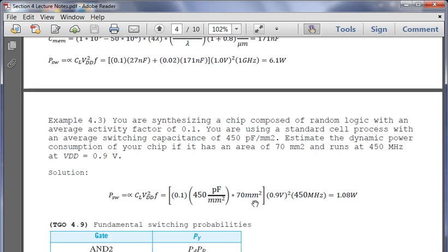So to tie into what you were asking a little earlier about figuring out switching probabilities, switching probabilities from 0 to 1, right? For AND, with two inputs, it has to multiply the probability on your A input times the probability on B. The reason is that both of them have to switch in order to get from that 0 to 1 on the AND gate. So therefore, it follows that the NAND gate is just 1 minus that.